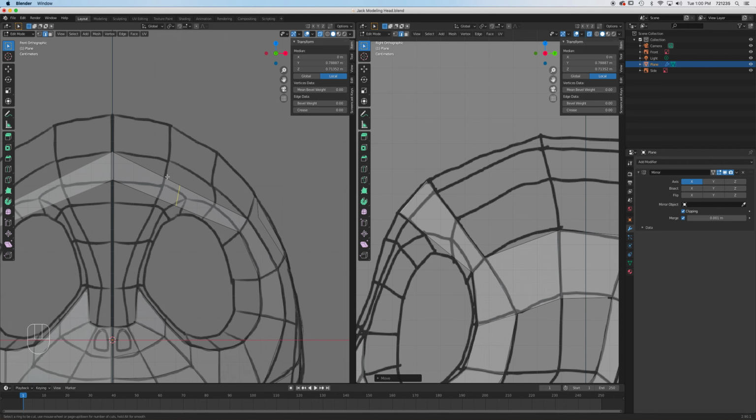So right here, I'm going to scroll the mouse. Okay, right there. So I scrolled it so I get 2 cuts, all right? And then I'm going to left click to confirm that. Now it's asking me where I want to slide. It doesn't really matter because we move points. We move it right there. And I got 2 cuts. So now we're kind of speeding up the process.